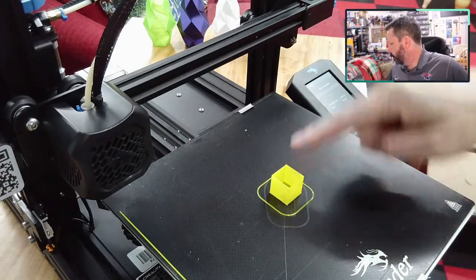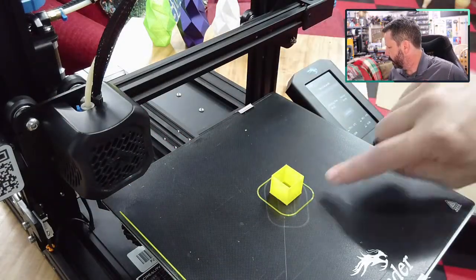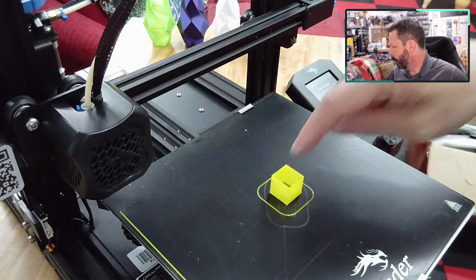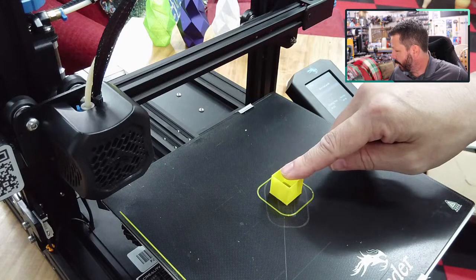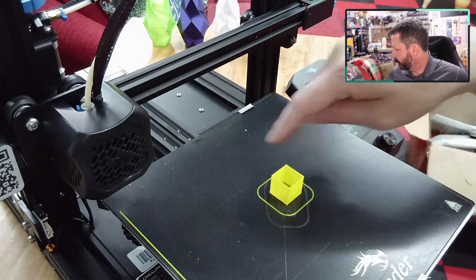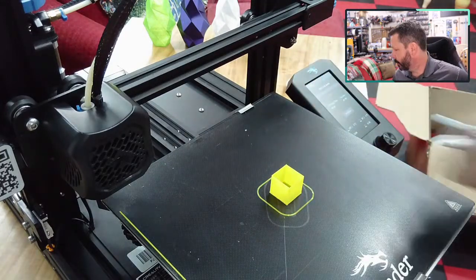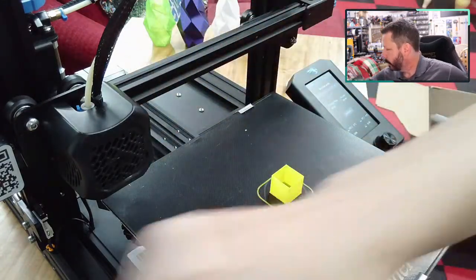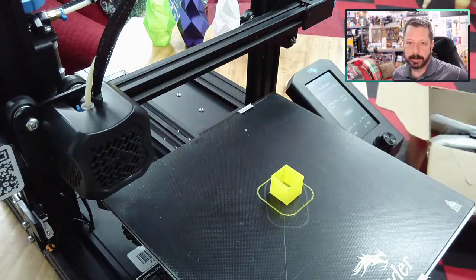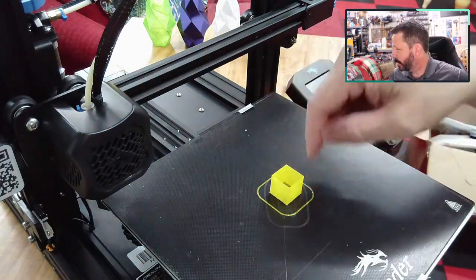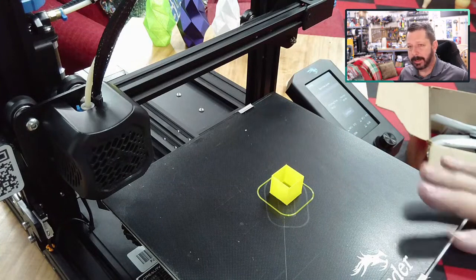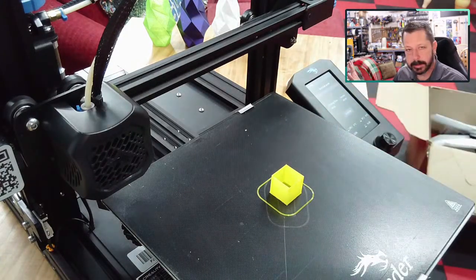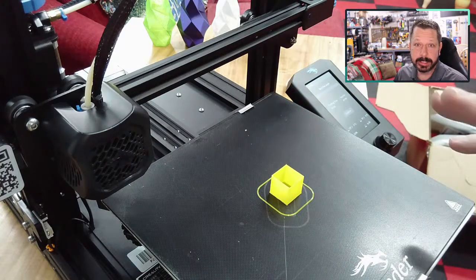So there's our little cube, one wall, spiraled, printed. There's our skirt. I just use that kind of as a marker to make sure the part is going to be where I want it to be, and that I've got a good flow of filament coming out. So it's also kind of like another little purge line. This one's the real purge line over here. But it's also just another purge, and it gives me a little bit of time if I need to make any adjustments to the bed level or Z offset, you know, how far the nozzle is from the bed, any of those things. It gives me a little bit of time to do that.